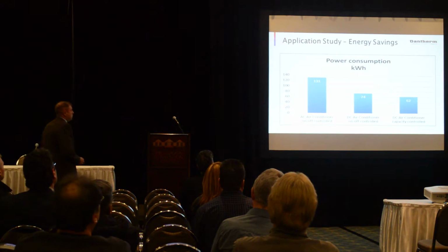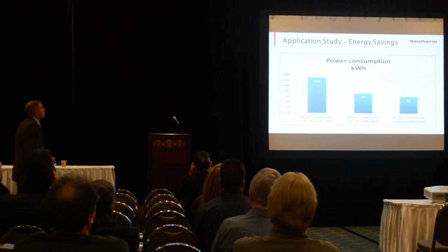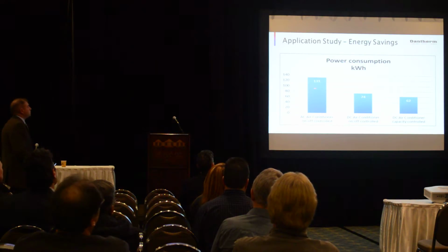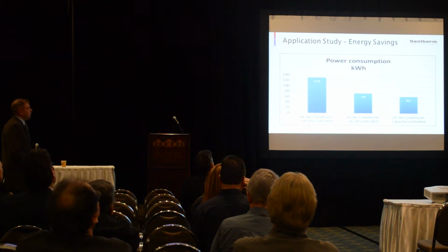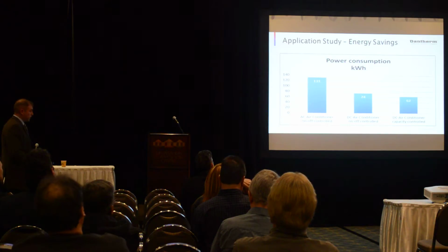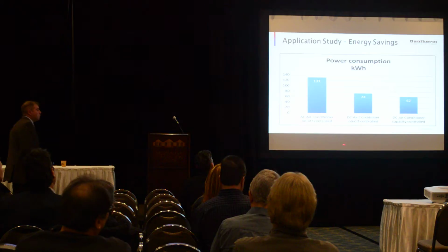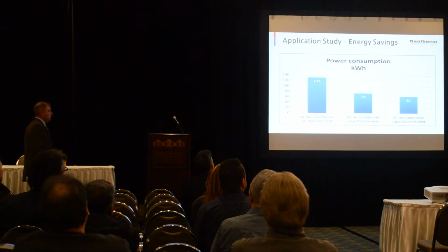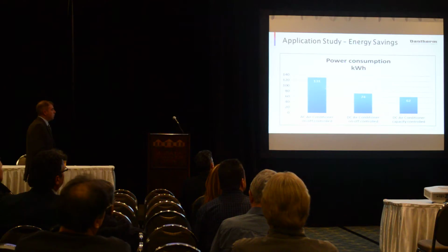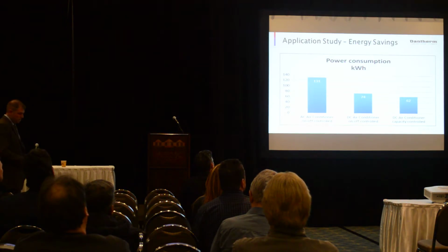That's the results. You can see the total kilowatt hours: 131 for the AC voltage air conditioner, which was just on off. The DC on off went down drastically, and the DC air conditioner, which is capacity control with that precise cooling, is down a little bit more. That's almost about 55 to 60% from the AC on off.